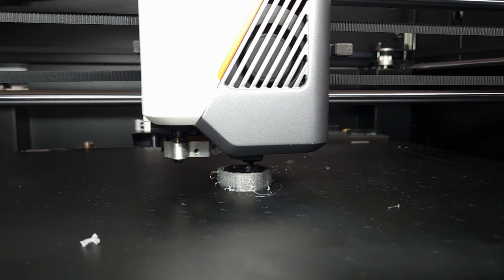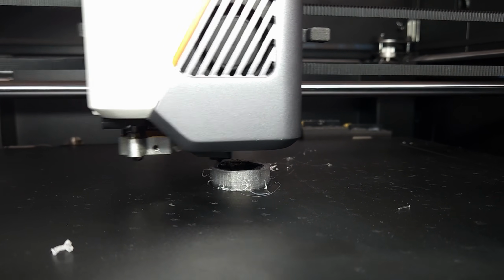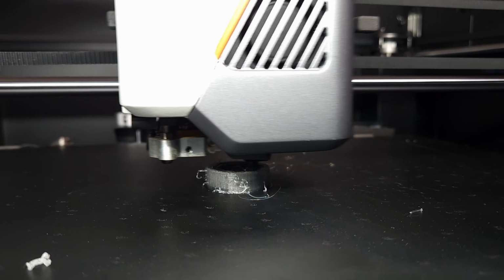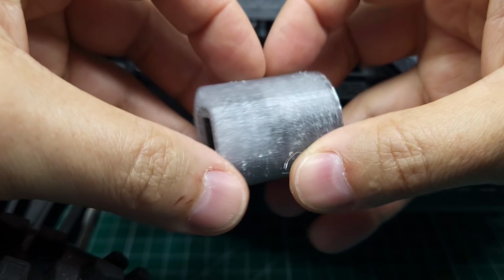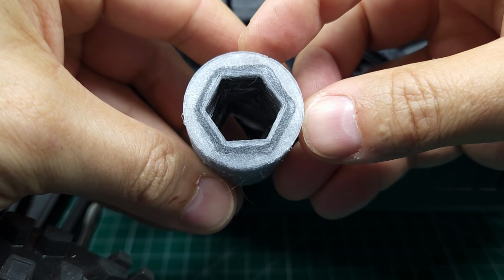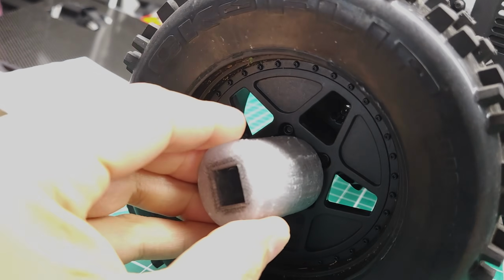I'm seeing some more stringing on this than on previous prints. I think that's because I've had my filament out in the moisture for too long, and that moisture gets in the filament, causes oozing, and that's what's causing these problems. However, even with that, this did complete and the reinforcement's in the right place, so let's see how strong it is. We're just gonna pop it on the...